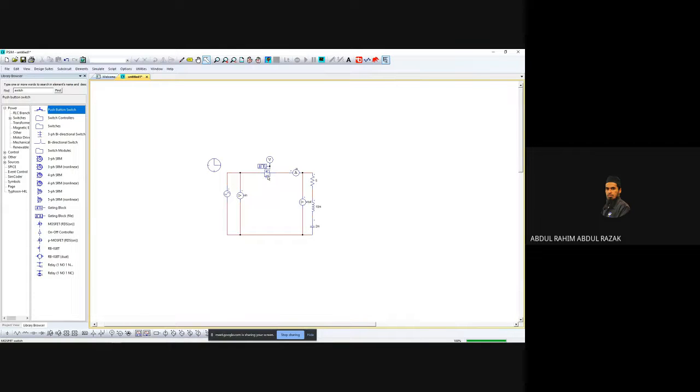Positive cycle, it behave based on the signal that you provide. But negative cycle, when the current returns from the load to the source, it will follow or flow throughout your diode. That is considered as your bypassing diode in the MOSFET. Most of MOSFET, they have bypass diode like this. But some MOSFET, by right, they don't have. Earlier MOSFET, they don't have this bypass diode. But due to application in the computers, most of it, they need a reverse or bypass diode. So in the recent module of MOSFET, they include together the bypass diode.